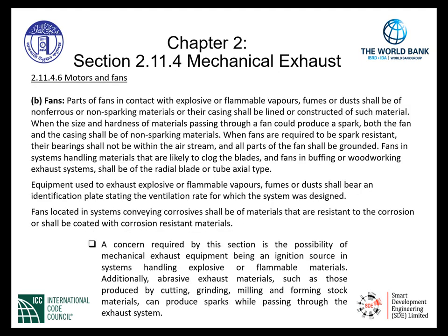Part B of Section 2.11.4.6 indicates requirements for fans. As such, parts of fans in contact with explosive or flammable vapors, fumes, or dust shall be of non-ferrous or non-sparking materials, or their casing shall be lined or constructed of such material.